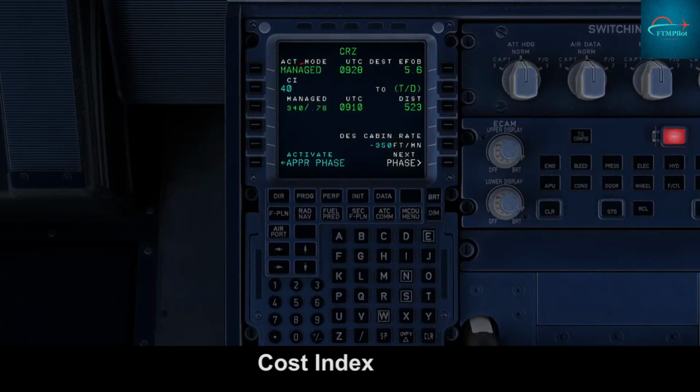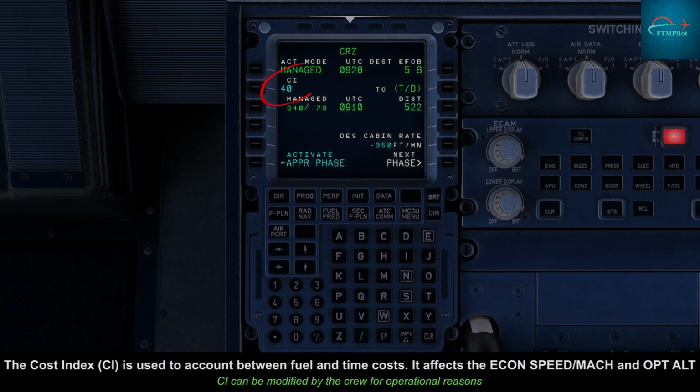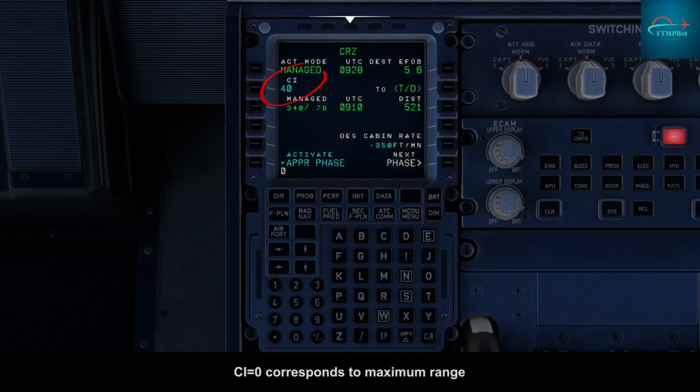Cost index. The cost index is used to balance between fuel and time costs. It affects the economy speed Mach and optimum altitude. Cost index equals 0 corresponds to maximum range. Cost index equals 999 corresponds to minimum time.